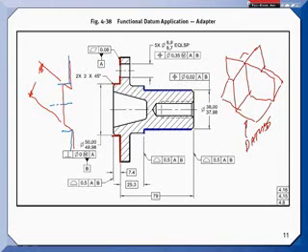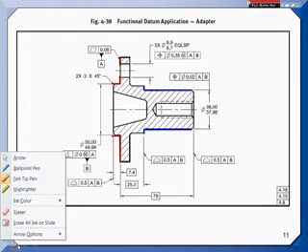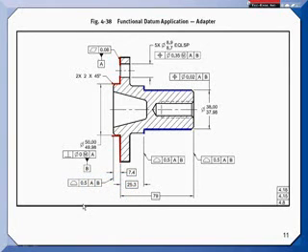Yeah, that's pretty much how I've been thinking of it. I think that at times Joel and I have gone back and forth thinking that the diameter that's 50 millimeters on the high side of 49.98, could you just not let that manufacturing deviation in size dictate where datum feature B is and not worry about it controlling back to datum feature A? And I've always, from all of your training and seminars, leaned towards, well, yeah, I want to control it, but it has caused confusion to myself, and I wonder if sometimes I am over tolerancing or over constraining a part on my drawings by doing that.